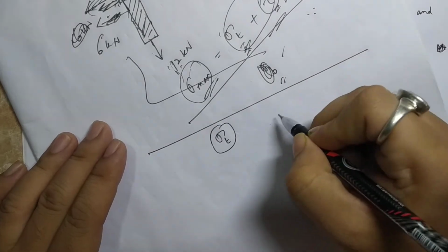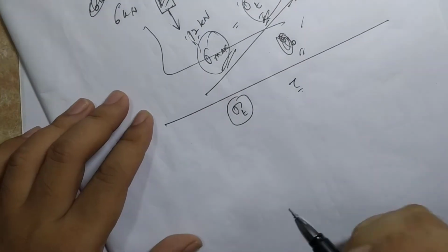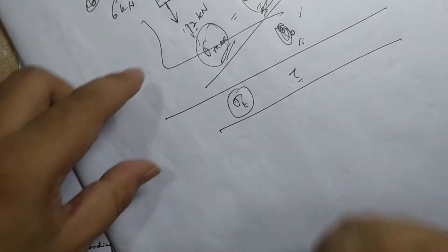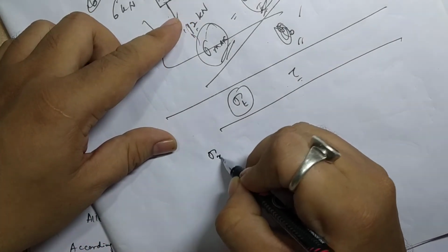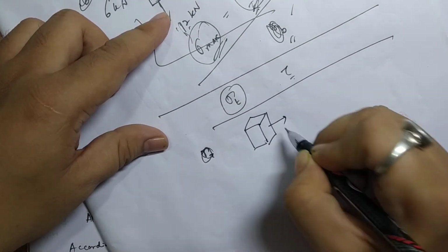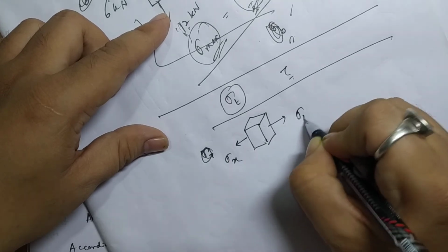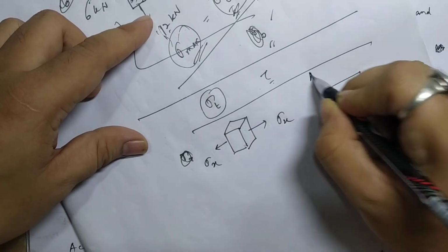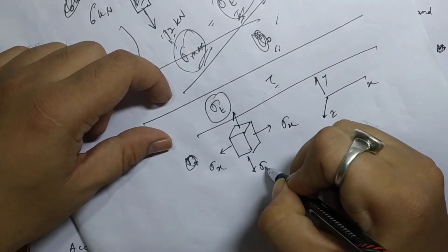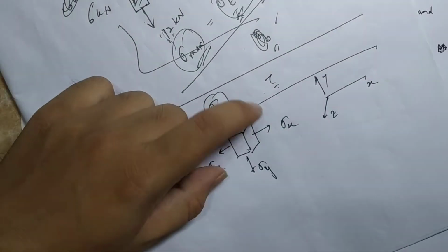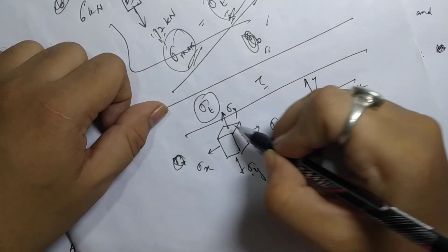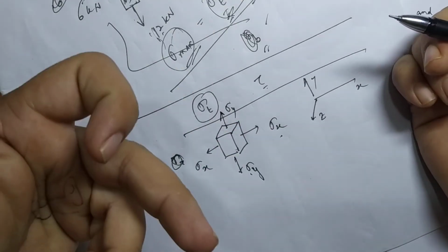Now to combine your tensile stress and shear stress, you have to go to your strength of materials concept. When we have any set of stress, consider this one: when we apply sigma x, this is x direction, this is y direction, this is z direction. Just consider only x and y direction. Sigma stresses are ordinary stresses. These are not principal stresses, by the way.